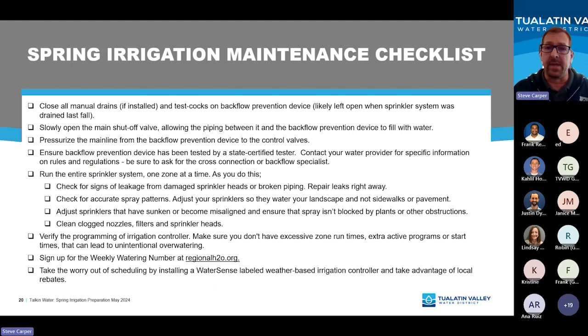Here we've provided you just a handy checklist for your spring maintenance tune-ups. I'm not going to go through each device, but again, just want to reiterate the importance of verifying how your irrigation controller is programmed. Make sure that you don't have additional start times or redundant programming. Again, that's the most common issue that I find when I go out and do site visits, a misprogrammed controller, and it's really easy to do because you're dealing with these tiny little LCD screens that can be pretty confusing. So again, it's really important to understand how your controller works and get it set properly.